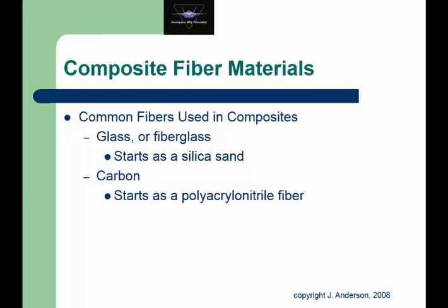The DuPont materials Kevlar and Nomex are both aramids. Kevlar, as a point of reference, has a tensile strength of about 2.8 gigapascals and costs about $30 a pound. Both of these are petroleum derivatives, and so they're tied to the price of oil, of course.